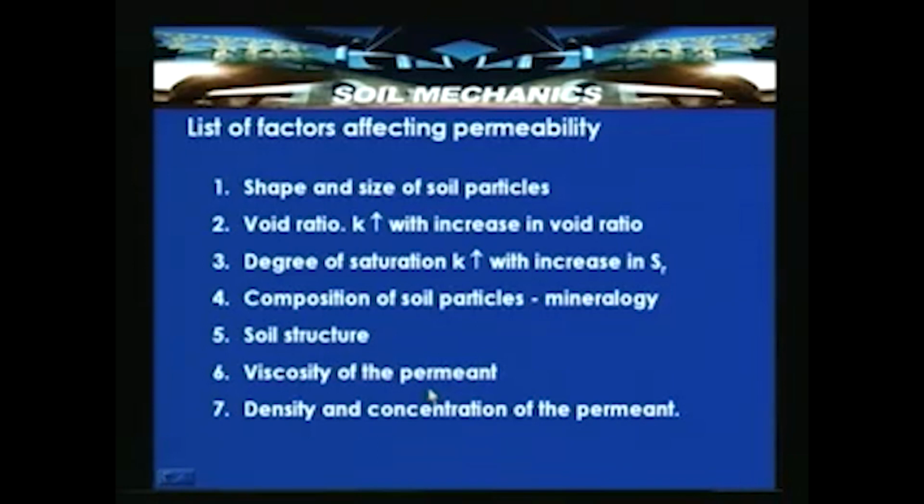We also discussed that based on Taylor's equation, k is proportional to de square, which indicates that with an increase in grain size, an increase in the permeability value can be seen. That is, if de is the effective particle size, a large effective particle size can have a larger permeability. So, that is what we have now discussed: factors affecting permeability, the effect of the grain size.